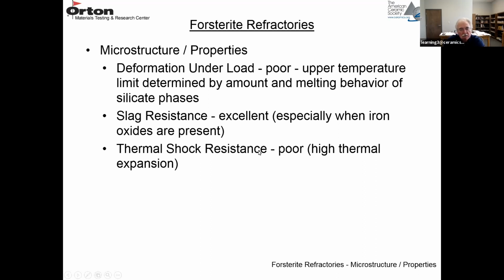Thermal shock resistance is poor because it's a high thermal expansion material. So just like a lot of other refractory materials, some of the properties are going to be a compromise. You can have a good property here, but then you have to be aware you might have a good slag resistance, but low hot strength and poor thermal shock resistance.